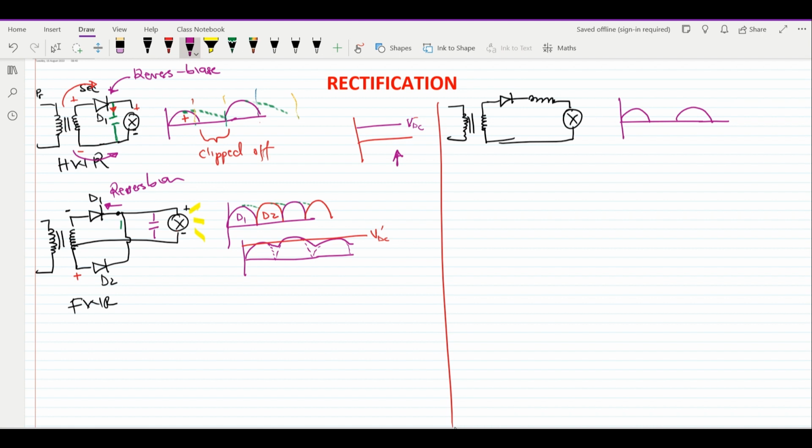This means that if the voltage supplied in this direction is 5 volts, the inductor will also generate through its magnetic field a voltage equal to 5 volts. But the problem is it then acts in the opposite direction, thus creating its own waveform around that, somehow cancelling out what we already have. But considering that sometimes it will have some voltage spikes, that will be a bit higher than what we already had.